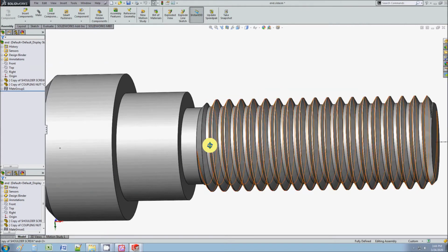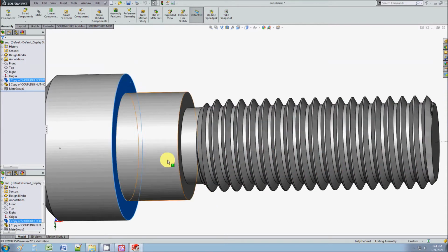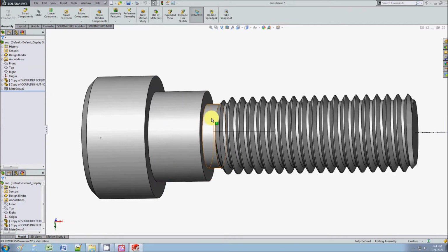Another feature to notice is this undercut. An undercut is a common feature in threads so that this bolt can hit bottom on this surface. If we don't put this undercut, if we keep it the same OD as these threads, there's a risk that the threads will stop in the middle of its end because of the way it's assembled. It depends on how it's assembled, but a lot of times to avoid having that seizing occur in the middle of the thread, an undercut is provided so that it clears off and allows the shoulder to be the stopper on the head of the bolt.